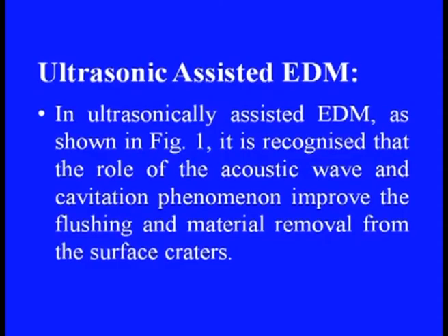In this process, the surfactant molecules act as a static barrier to separate the agglomerated aluminum powder and disperse them within the dielectric, thus improving the surface finish. Now, let us move on to another process that is called ultrasonic assisted EDM, also called UAEDM.